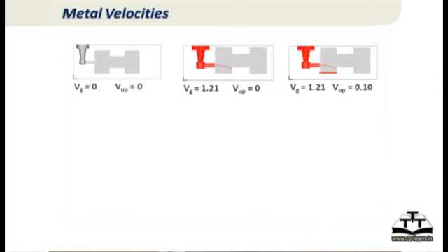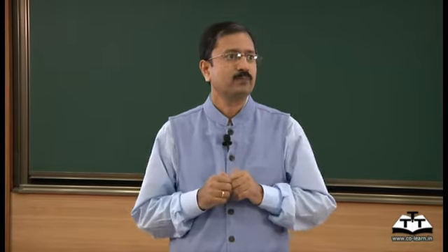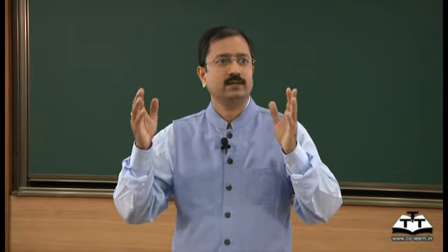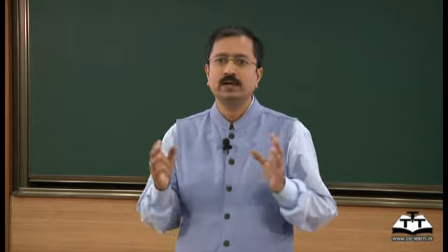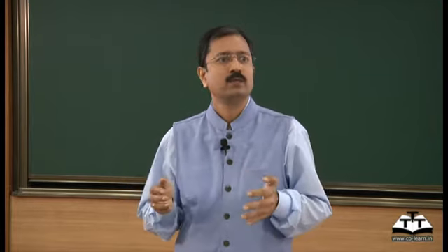Okay. Now we have to track one more velocity, which is the vertical velocity of metal in the mold. This velocity is the rise of metal in the mold cavity. If you assume the original picture, we said the velocity is reducing as the head is reducing, and assume a constant cross section area of the casting, let's take that for a starting point.